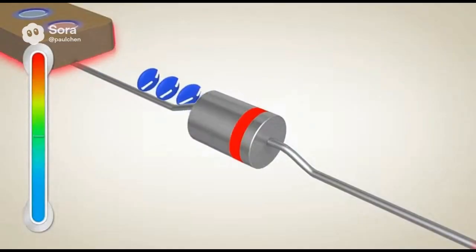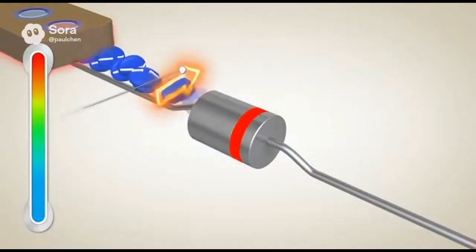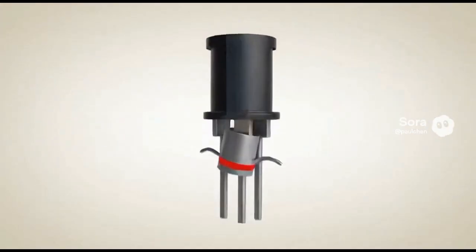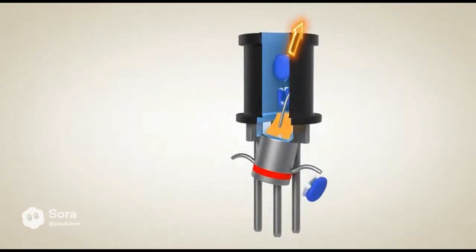The base emitter junction behaves like a diode. In a silicon transistor, this junction turns on at about 0.7 volts. That's why the emitter voltage naturally sits about 0.7 volts below the base. This relationship comes from physics, not from design choice.